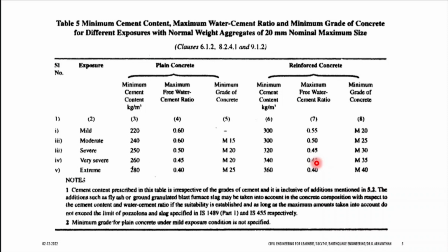They will call. My clients have not called me till now. I have made a 2000 liter water tank. For a G plus 1 storey, I have installed a 2000 liter water tank on a slab. 2000 liters of water is how many kg? 2 tons of weight. What is the live load you are taking for design in a slab? 1.5 kilonewton. 1.5 kilonewton is how many kg? 150 kg. You are designing the slab for 150 kg, but when you place the water tank, you will be